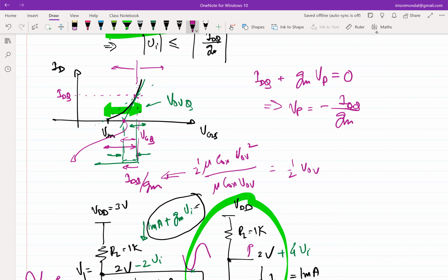Right. So this is one problem if you have many gain stages cascaded one after another. What ends up happening is that the final stage always sees a lot of distortion, because the input to the final stage will be swinging much more than the input to its previous stage, and so on and so forth. So that's why in many open loop designs, even though you might want to cascade multiple stages, this distortion is something that you'll have to be careful about. Any questions before we break?